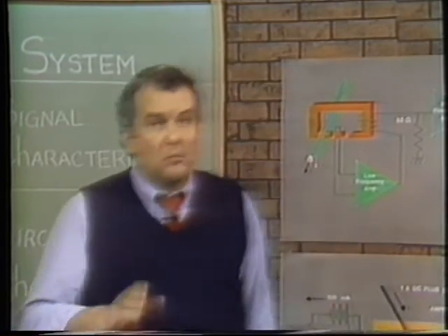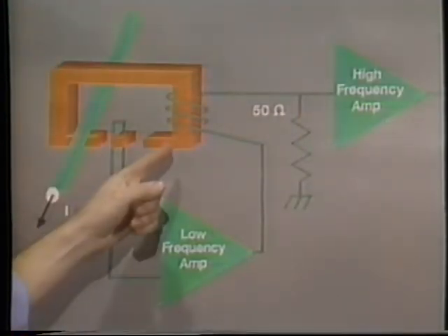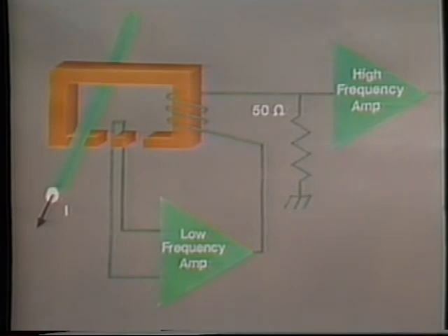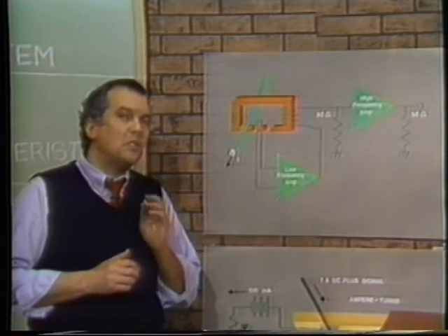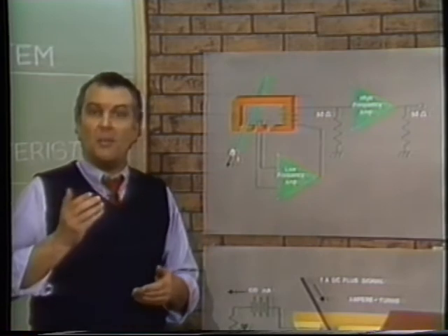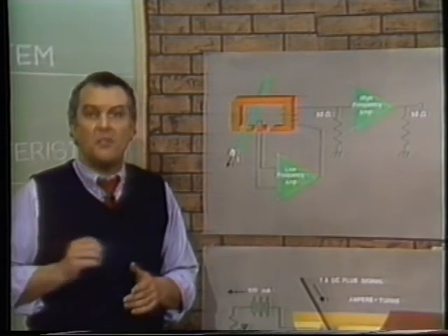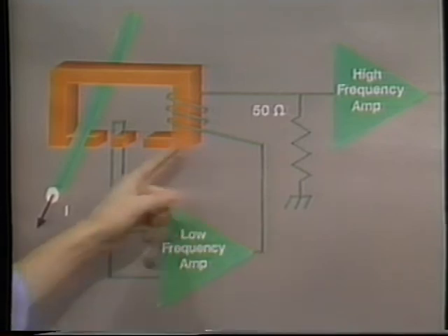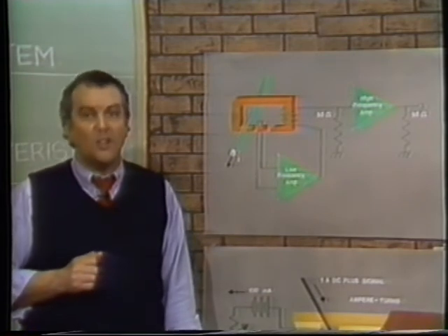AC and DC responding probes have a little bit more of an interesting design. In addition to the passive current transformer, we add a Hall effect device for the DC and low frequency AC components. The frequency response of the Hall effect section is carefully matched to the frequency response of the transformer section. As one rolls down, the other rolls up. Their summation is a flat frequency response from DC to about 50 megahertz. Part of the Hall effect output is also fed through the transformer section to cancel the DC flux field. This avoids saturating the transformer in the DC and low frequency range.